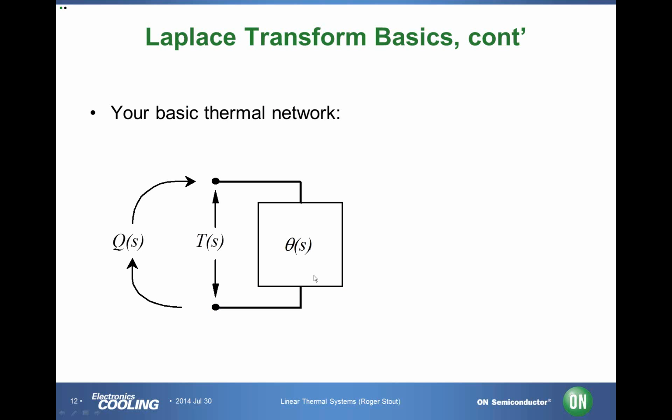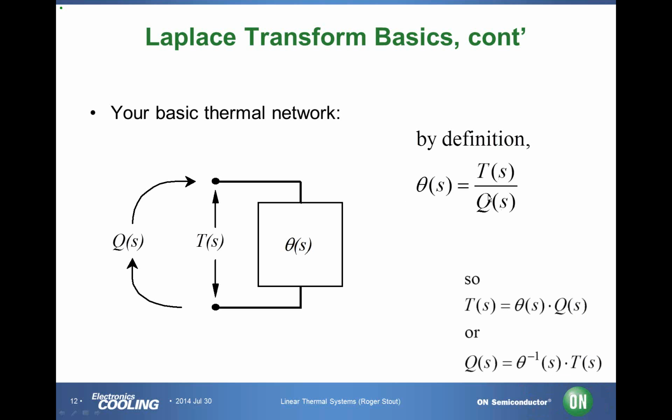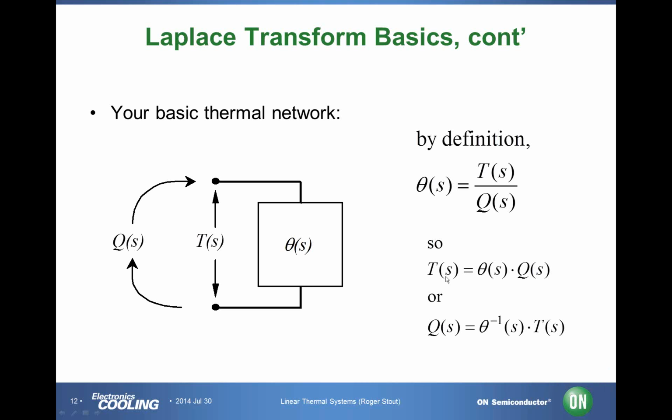And the basic idea behind Laplace transforms is that you've analyzed your system and you think of everything in terms of the S-plane, where we have a system that's described by theta of S. You can apply a stimulus, which is a temperature, let's say, measured at this outside, or the stimulus that's applied is Q of S, the heat input. You can define the transfer function of the system, theta, as the ratio of the applied stimulus Q to the response T.